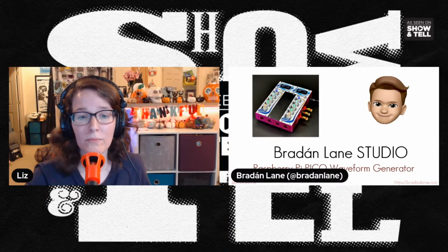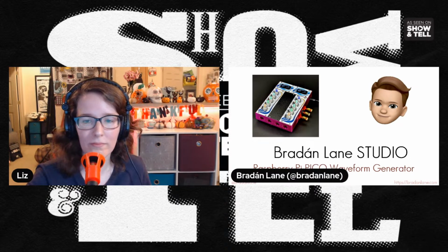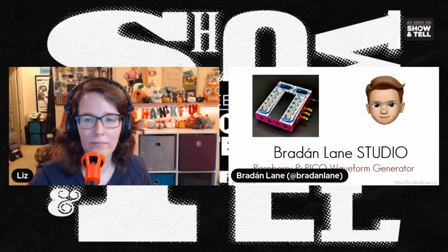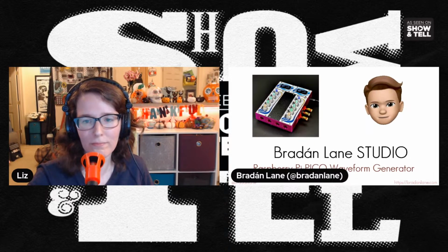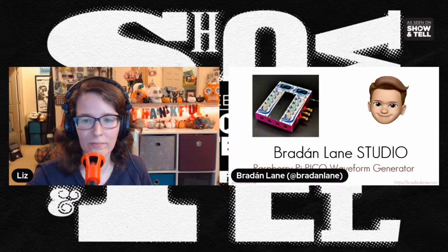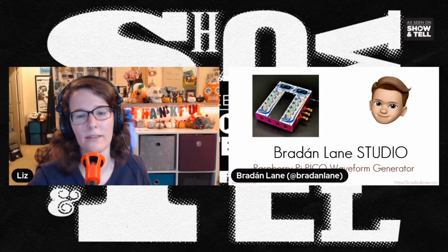And I said, well, that sounds really kind of cool. And so they were using a Raspberry Pi Pico. And I did some research and did some digging around, and I found some bits and pieces, and I was able to glue it all together for taking a Raspberry Pi Pico and something that's referred to as an R2R, which basically says it's a resistor and it's 2x of a resistor. And you can create a DAC, a digital to analog converter, just out of resistors.